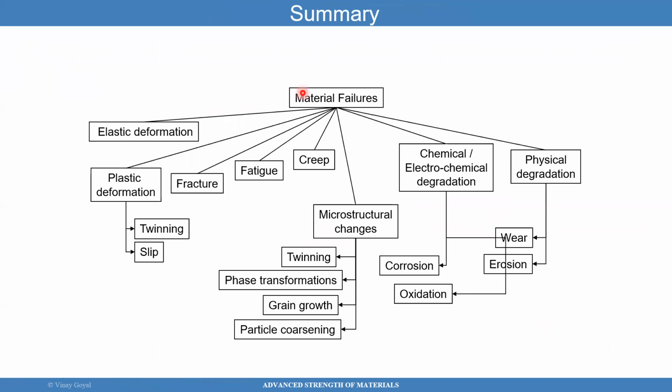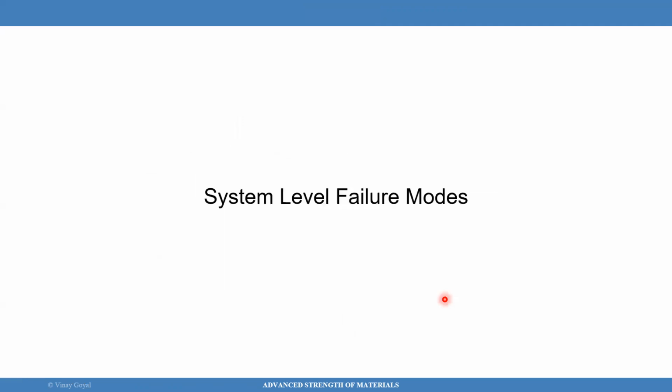So there are a lot of different material failures. I'll pause there for a second so you can absorb it. I covered most of them, though not every single one. But it's a good map of all the different failures you're going to have. I will try to go off memory: you have strength, fatigue, low cycle and high cycle fatigue. Then you have the environmentally induced failures like hydrogen embrittlement, hydrogen-assisted cracking, corrosion, galvanic corrosion, buckling. Then you have other failure modes associated with a flaw that can propagate the failure, wear, and then erosion. I think I covered most of them, oxidation and things like that.